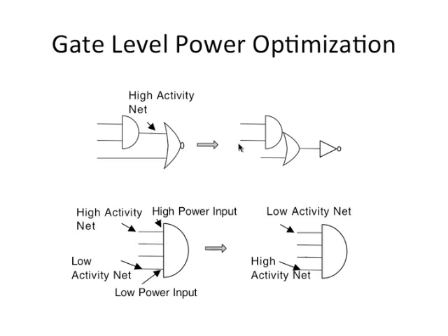So this is why you also have a lot of gates in a standard cell library. You can always make any Boolean function using just a NAND gate, right? NAND gate is good enough, and an inverter, and you are done. That is a universal gate. In fact, you don't even need an inverter; just a NAND gate is good enough. But it doesn't lead to very efficient designs. So you need to have these kinds of compound gates which help you to reduce area, reduce power, etc. And so you need to have a bouquet of such gates, so that the tool which is synthesizing this can choose the most optimal gate to reduce power and also reduce delay.